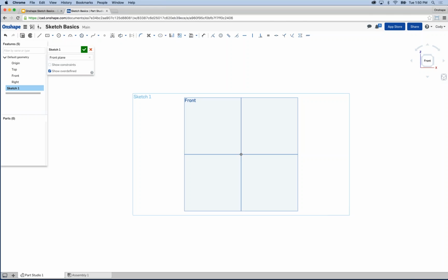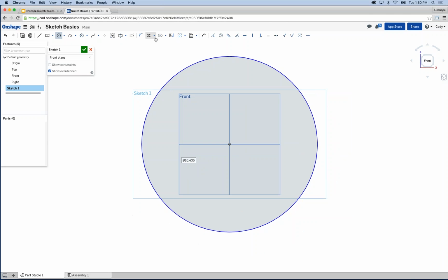Now, another frequently asked question. Let's sketch a circle real quickly. Can I take an individual piece of geometry and split it into multiple pieces of geometry? And this is particularly helpful for things like a loft, where I want the same number of vertices on each sketch point. I can select a command like split and split the individual pieces of the sketch.